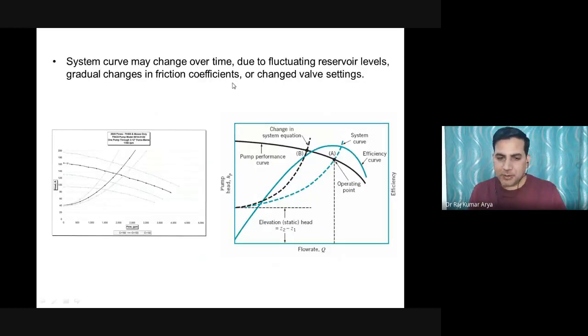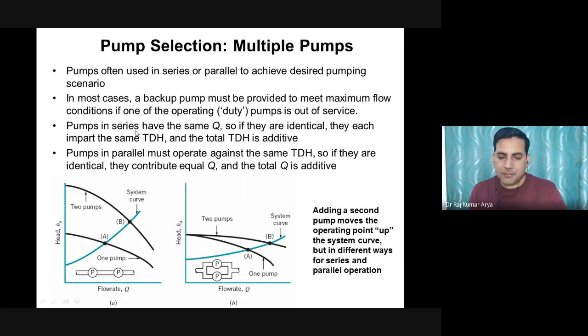So this is another graph of the same type. Now, this is what I was talking about here, the multiple pumps. So this is what you have, two pump combinations here. This is pump A, this is pump B. Now what will happen here, one pump combination and two pump combinations. Let's say one pump can discharge the fluid up to 10-meter height. After that, this is here, pump 1 and pump 2. So this is the series combination.